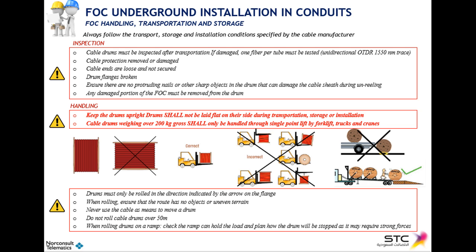And last but not least, pay attention when you are unloading the trucks and using a ramp, because these cable drums may be very heavy. So you have to plan in advance how you are going to control the force of the cable drum rolling down the way. Do not do that without the proper planning.